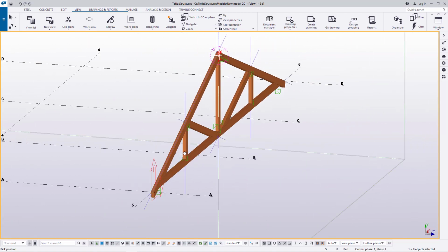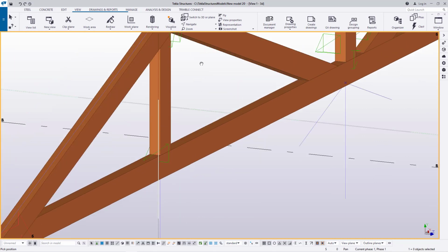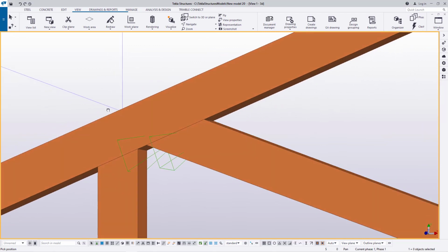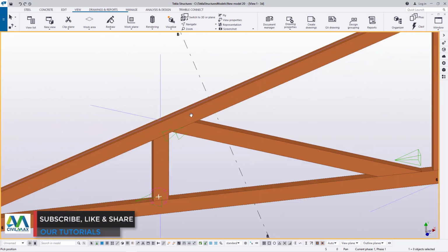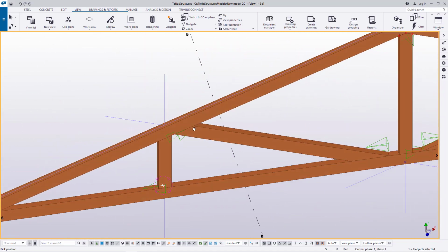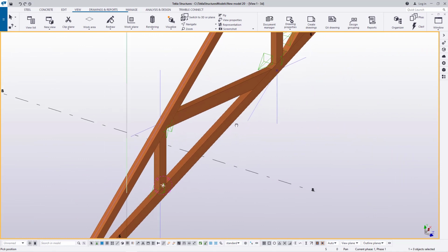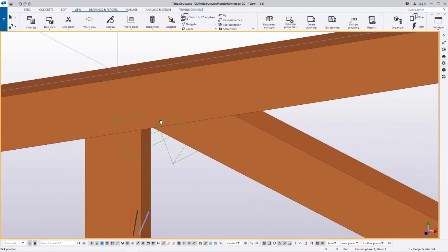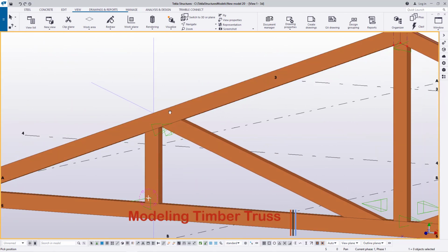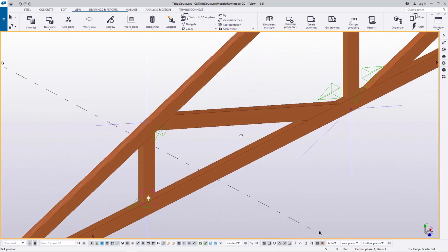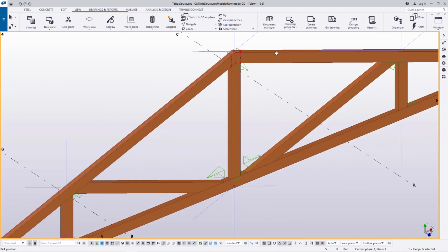And prior to that, let me just turn this round so that you see how it looks. I'll just turn it round and you see how this one looks. We can either decide to use nails to create connection, but nails are not really trustable because timber sometimes wears out, and the connection tends to sabotage the loadings that are on top of it, which may sink in, which might be disastrous to people living under this roof. So nowadays the light gauge profiles are taking over, people running away from timber structures.